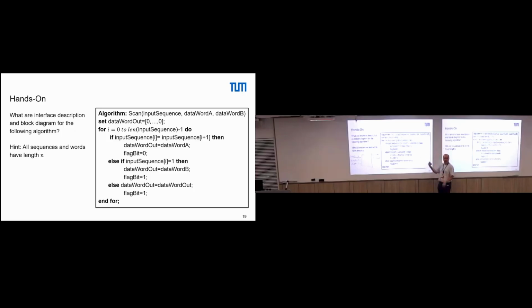For each clock cycle, we have something else, and we need to compare this. So we need some kind of a comparator. This comparator should tell us if the input in a specific step is the same as the input in the next clock cycle. So we buffer the input signal. All of this is n bit wide, okay? We buffer the input signal and compare the current input signal with the one from the previous clock cycle, okay? That effectively implements this line of code.